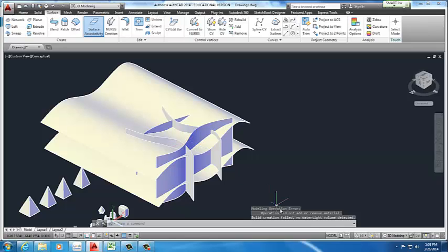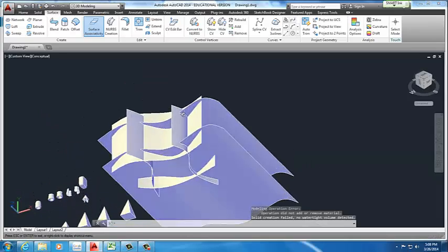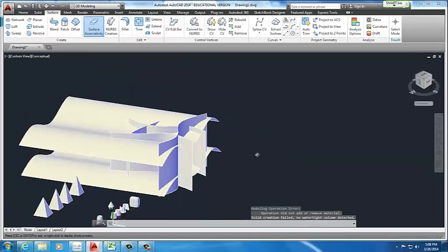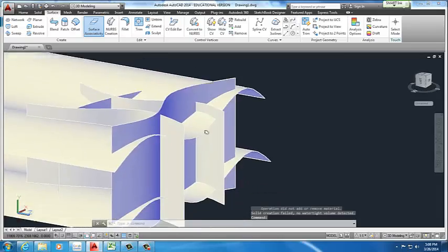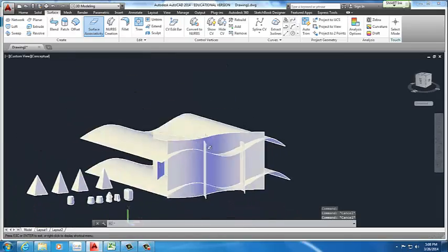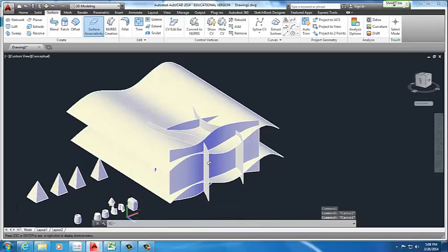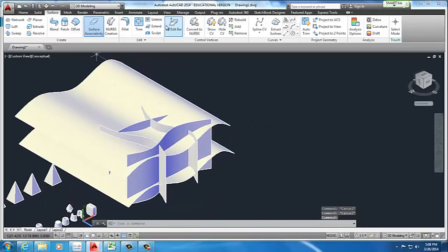It is one piece, and now we can try using the sculpt command to get the part. Let's see, solid creation failed, no watertight volume detected. There is an issue with this whole design. And that is the problem, that I don't like using sculpt because it creates that issue. Alright, let's try that one more time.